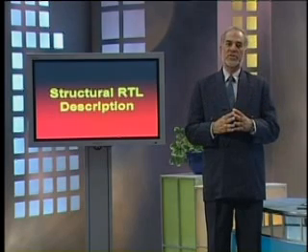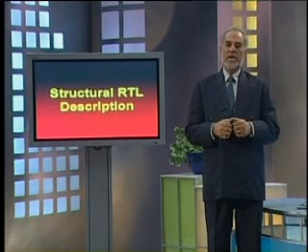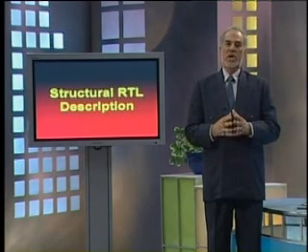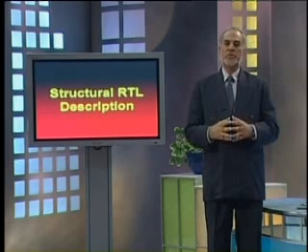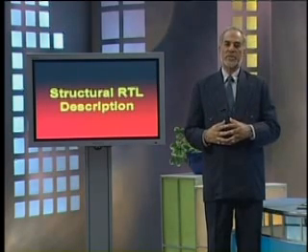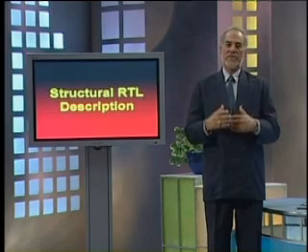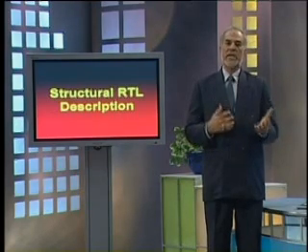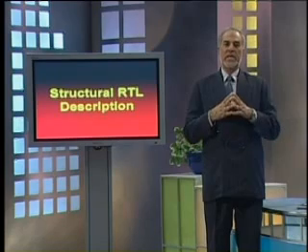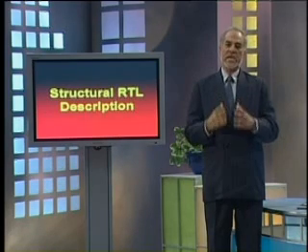So for all instructions, we had first 3 steps for fetching a particular instruction from the memory, and then execution has a variable number of steps, which could vary from 1 timing step up to 5 timing steps, altogether the maximum being 8. And at the end of each sequence, the timing generator is initialized back to 0. So every instruction starts from T0 and ends at T4, T5 or up to T7. We were going through the execution of different instructions for our Falcon A processor.